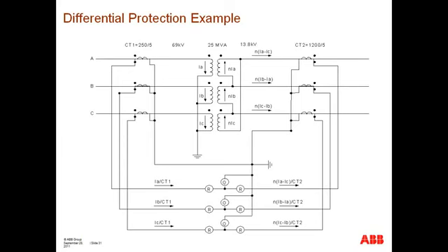Okay. Let's see, what else do we have? Why was the CT connection on primary Y and not delta? We'll discuss in just one second, because that's part of the idea behind this example. Okay, so in this particular case, we have Y-connected CTs on both high voltage and low voltage side, although we have a Y delta connection.